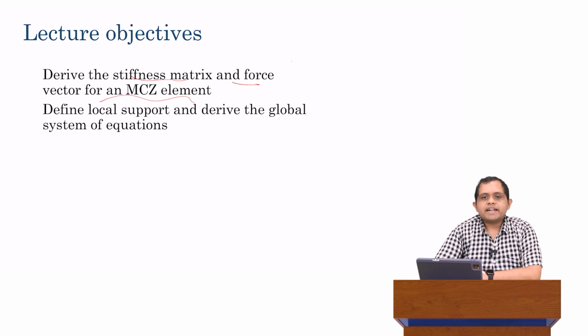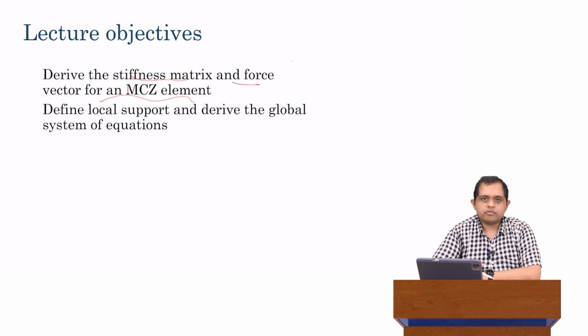As a reminder, in the finite element method, we start with a differential equation. We end with a series of algebraic equations. And it's not going to be a small number of algebraic equations. Practically, it will be millions of algebraic equations. We end up with a large number of algebraic equations, which you can write compactly as Ku = F, where K is called the stiffness matrix. So let me write it down. K is called the stiffness matrix.